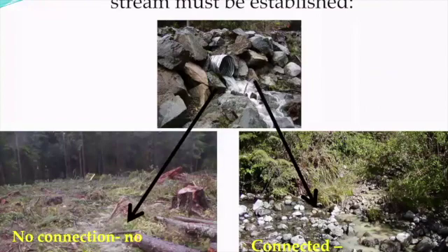Another option would be you have a ditch line that runs directly into a creek. In other words, everything upslope of that ditch line is now part of the problem. And everything that you calculate coming off that cut bank road, any skid roads, anything flowing into that ditch line upslope is tallied when you're estimating the amount of fines that are delivered to the creek.